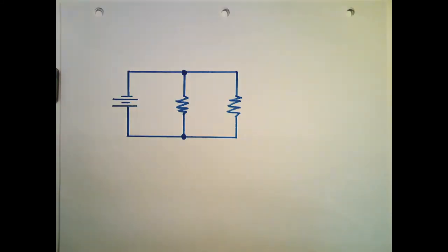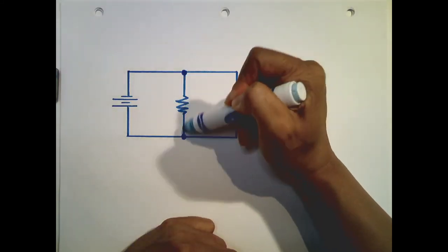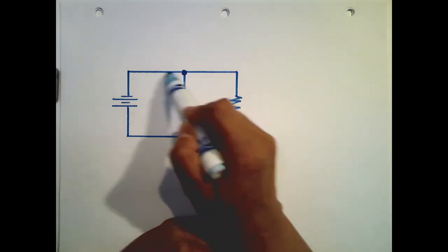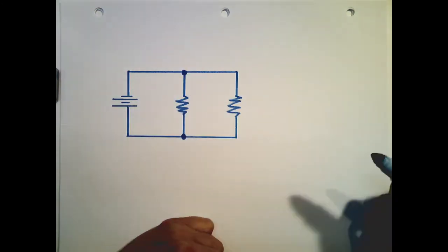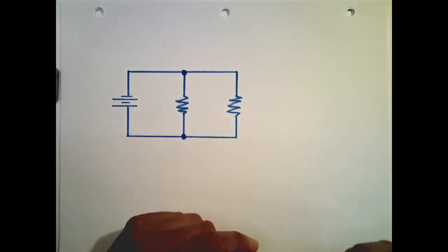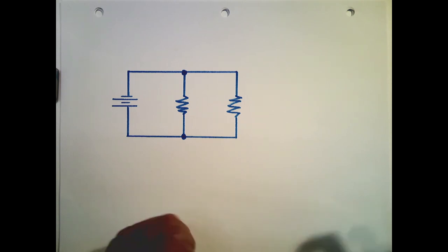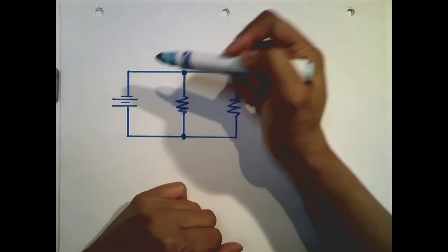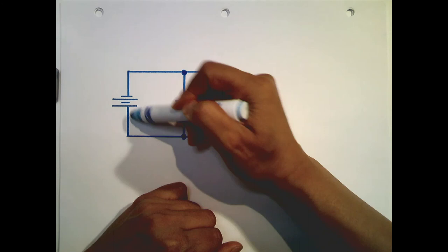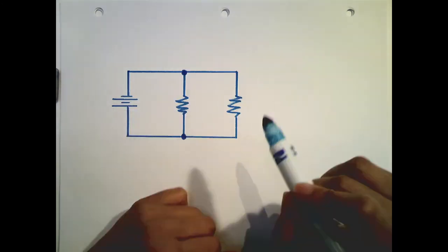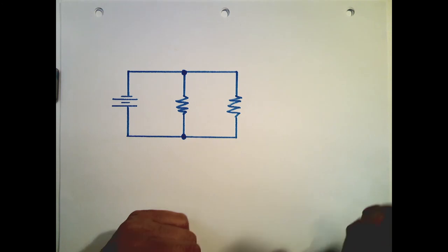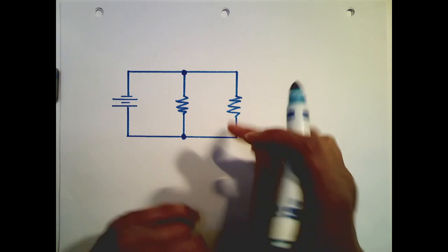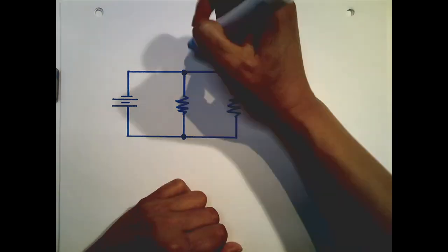And so when I say there's 3 branches, there's this branch over here, there's this one over here, okay, and then there's this one over there. So there's 3 branches because there are 2 junctions. And that's basically how you define a branch. Although the loop, according to the voltage law, this is a loop and that's a loop, okay? Technically, this is also a loop as well. So 3 branches and 3 loops, I guess, with the 2 junctions, all right?